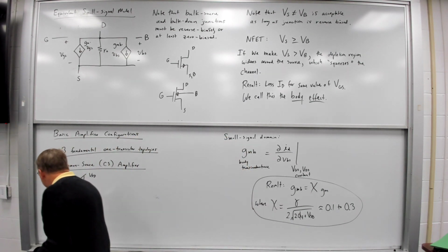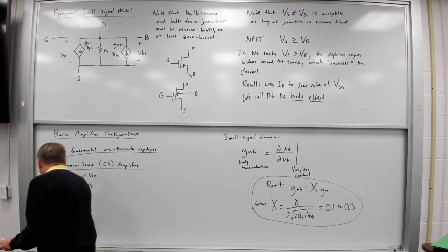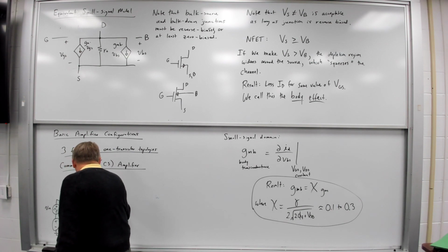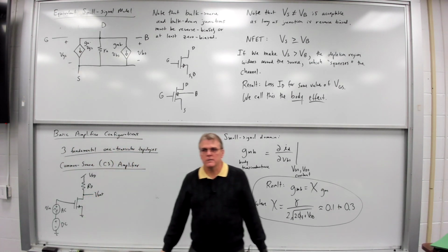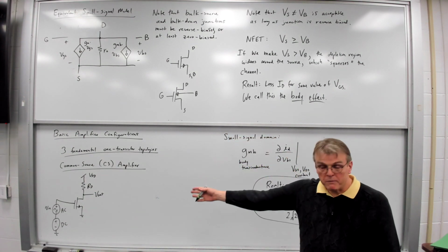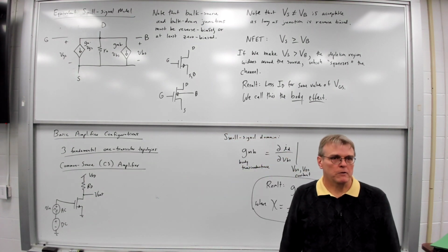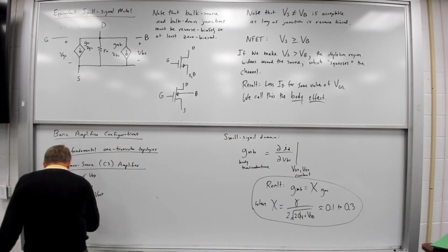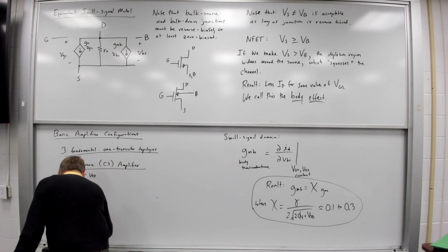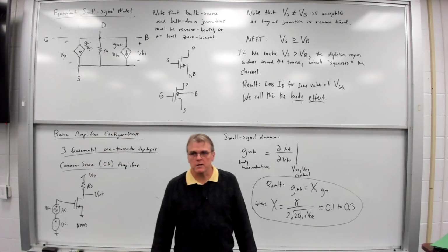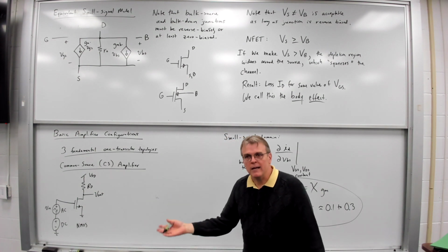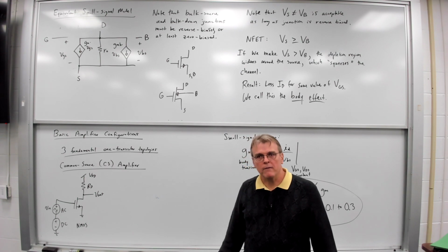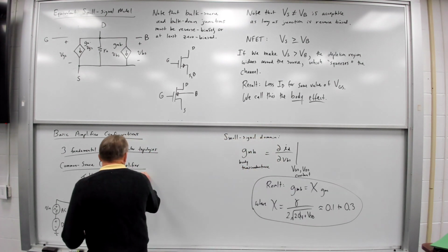In this case, the AC source is our input voltage. We take our output, V out, at the drain of the transistor. So we've already looked at this. We've actually analyzed this simple amplifier circuit already. Now, this is an NMOS circuit, right? But there's no reason why I have to use an NMOS transistor. Anything I can do with an NMOS, I can do with a PMOS. How would I draw a simple common source amplifier in that way? Well, let's do it. You do it like so.